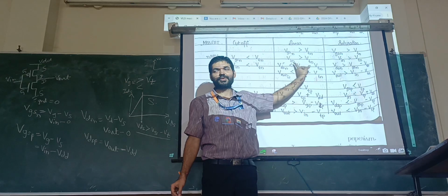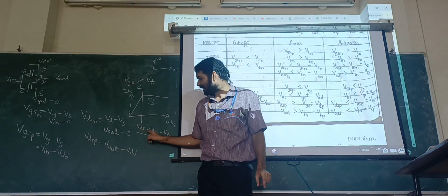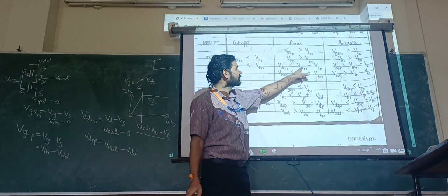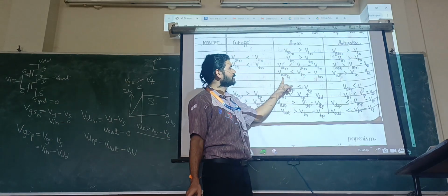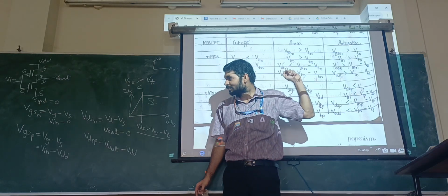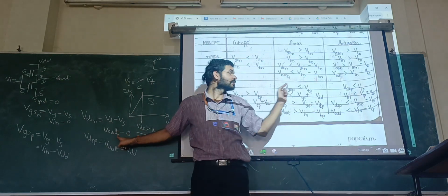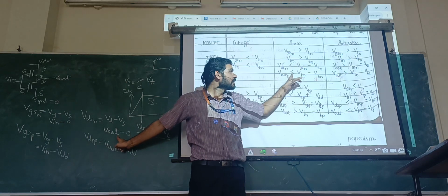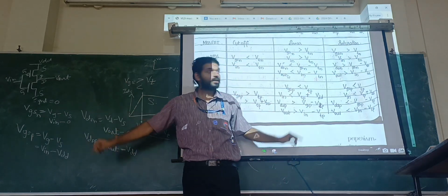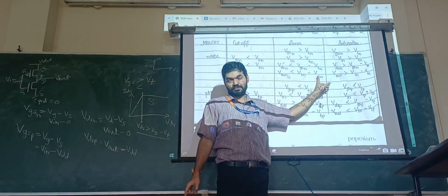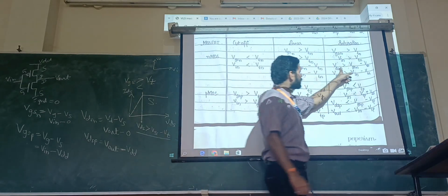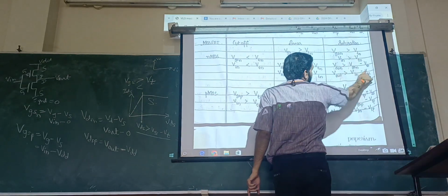Because NMOS is VDS less than VGS minus VT, it is in linear region. Okay, substitute. VDS N is Vout, less than VGS N minus VTN, Vin minus VTN. Okay, critical, greater than comes.